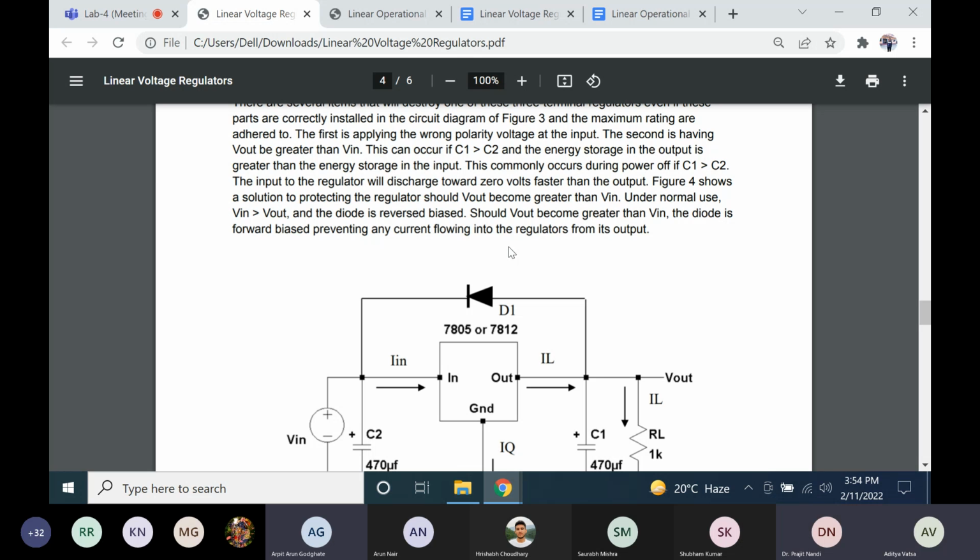The normal question should come, why should V out, the way that we are showing you the circuit, why should it at all be higher than V in, right? There is no reason, right? In this circuit, yes, it doesn't seem like there should be a reason, but in the practical world, and the car can be a good example. Basically, in industrial electronics, if you are doing industrial instrumentation, you will see many such examples where charges can be dumped. It can be even things like electrical discharge of some other circuit. Some other circuit is getting discharged and it can dump a huge amount of charge onto V out, and that can create a reliability problem. So the D1 diode that is kept takes care of a reliability issue.